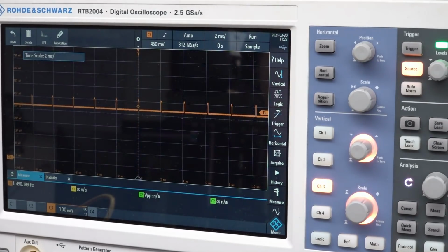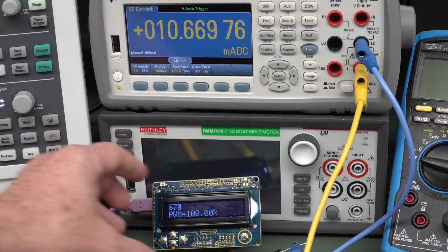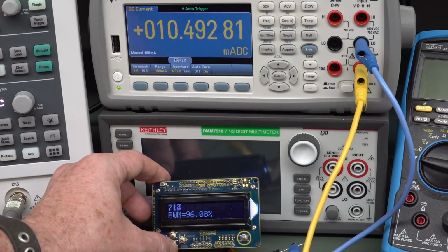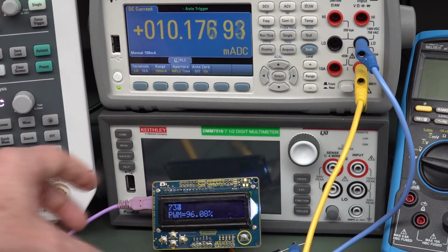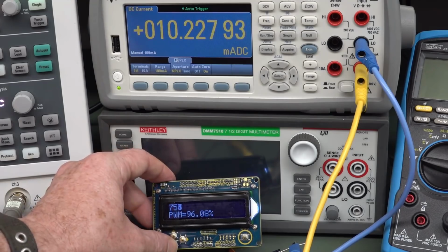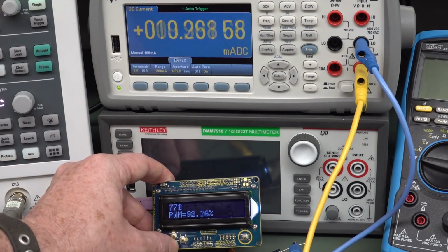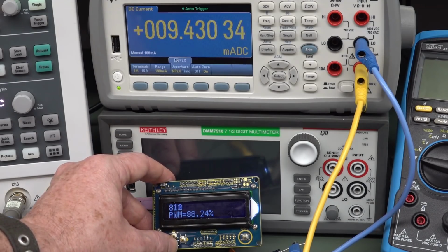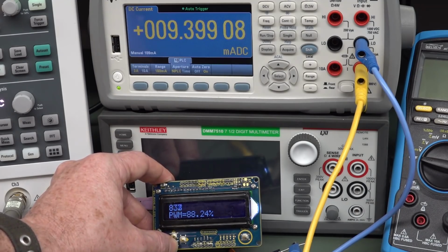And then if I change my PWM again, there you go, a bit bigger, 84%, it just gets bigger, but it's still working. So let's actually test this with the power consumption, 100%. Okay, there's no switching, but once you start switching that VCC line, it's lowering the power consumption, even though the 5-volt rail is still, you saw the waveform before. It's not like it's dropping it down to 3.3 or anything like that.